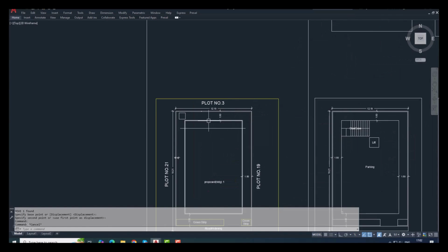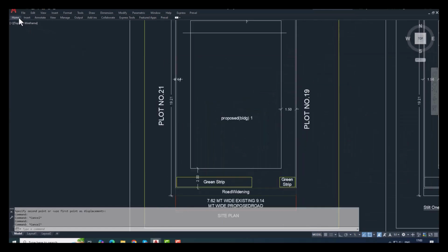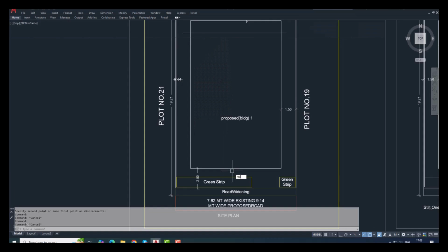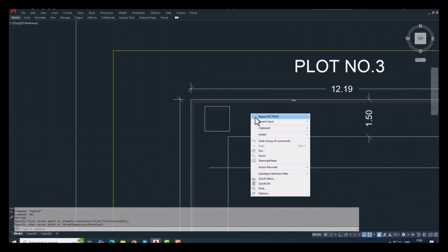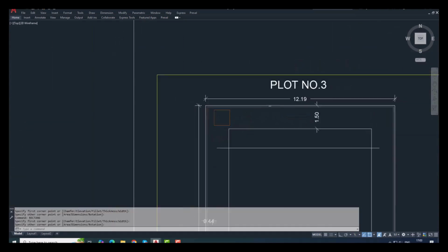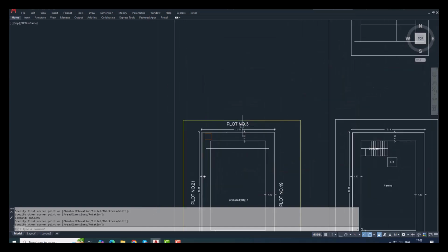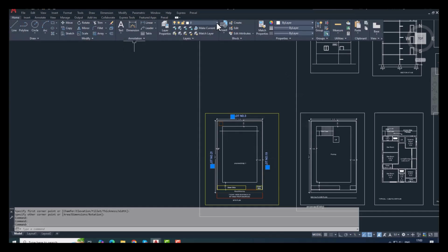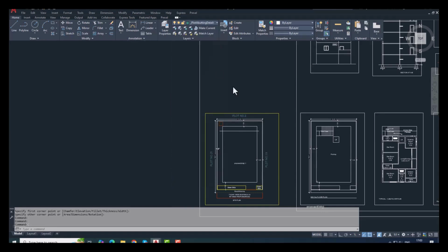Now, we are going to mark the main entrance area. The entrance is an accessory. As you remember from the previous video, we have it in the mark accessory use. We mark a rectangle for all the amenities that come under accessories using the accessory use layer. Now we select all the details outside the plot area and we put them into the plot abutting details layer.